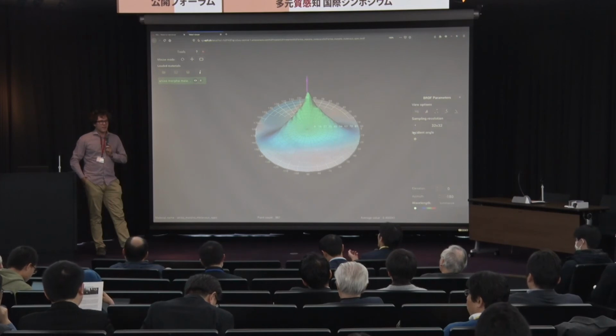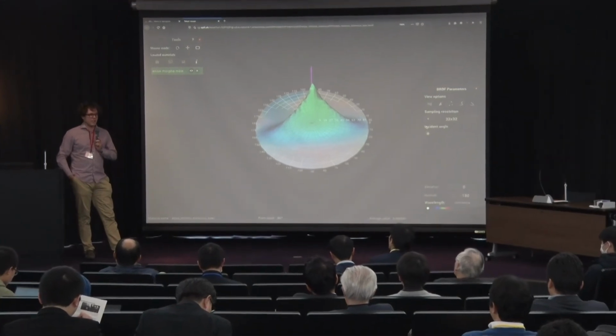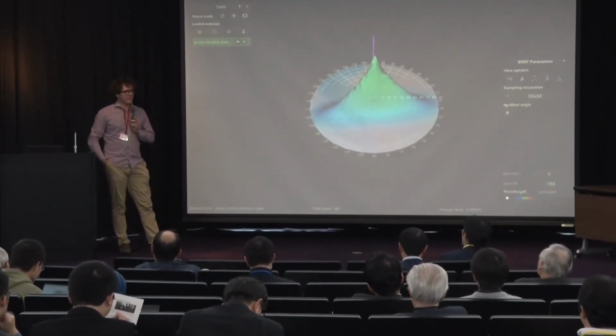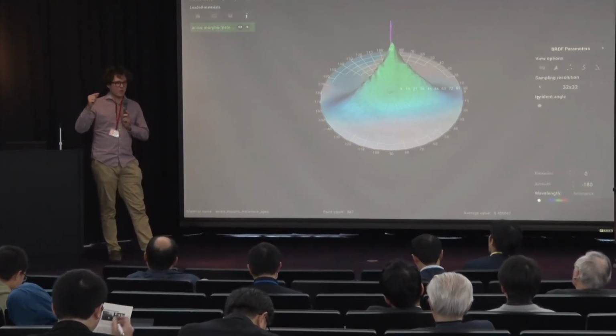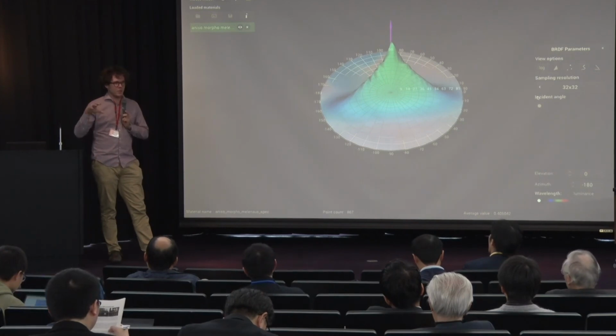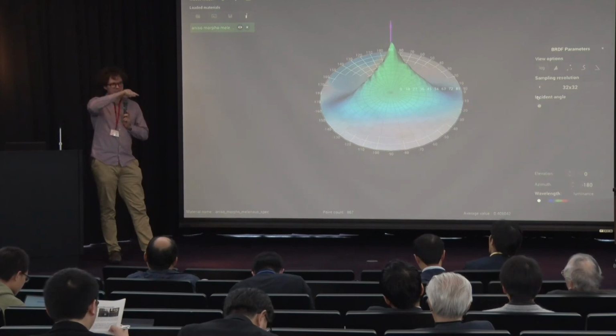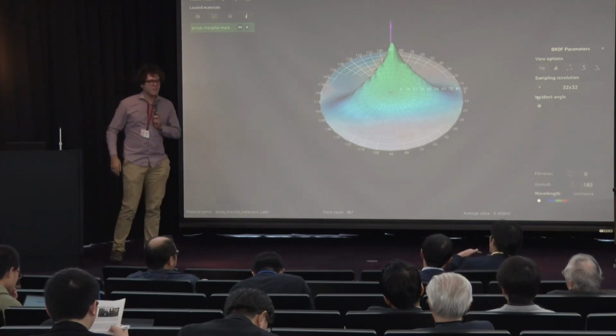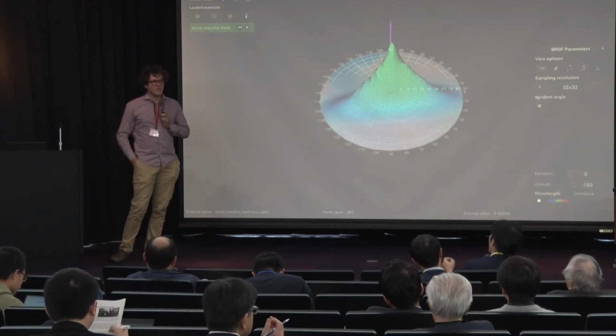But you need to have a 3D model or a lighting model of that. Aha, that's the sun actually, right? So we know exactly the way that the sun moves throughout the day and throughout the seasons. So you will probably want to simulate a whole year. That's a pretty long rendering because the sun is constantly in different places. You need a perfect model of the building and the materials.